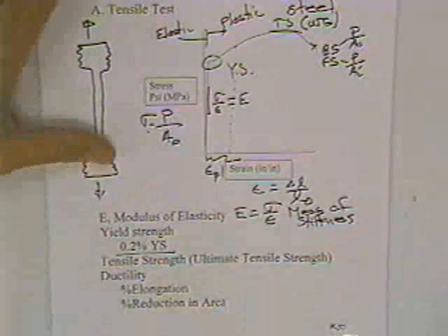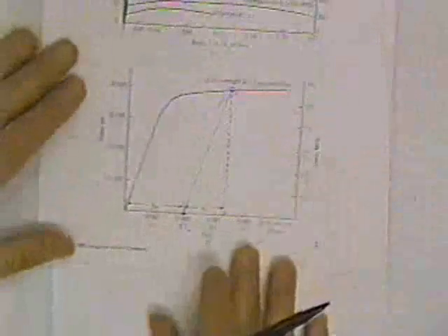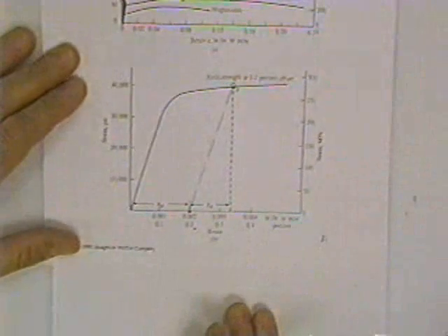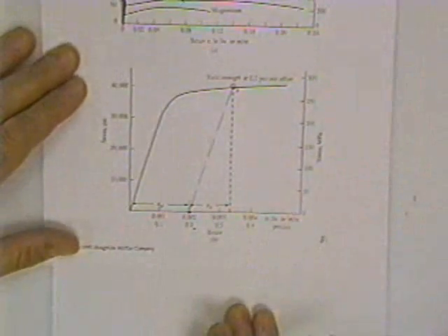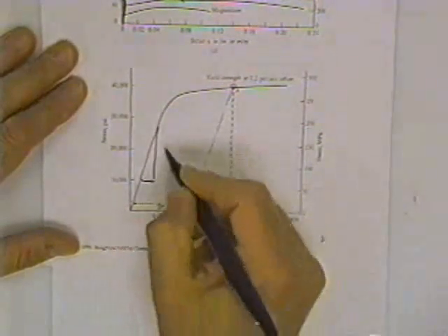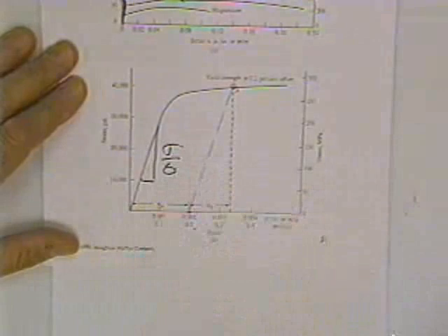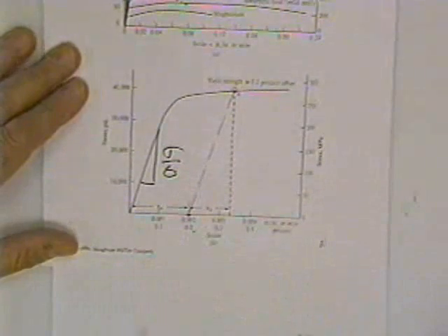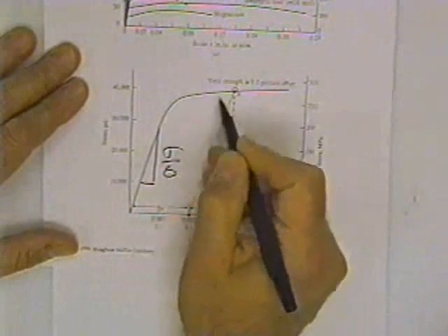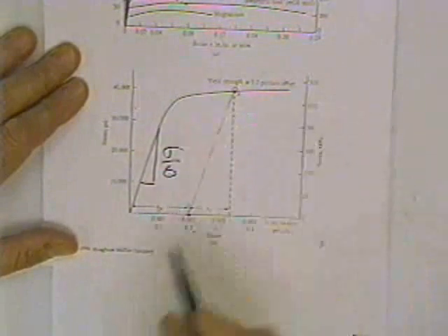And if you go to the second page, page 31 here, there's an example for an alloy showing the 0.2% offset yield. Here's the elastic portion, would give you the Young's modulus, and now you would say, well, where's the yield point? If 5 people did that, you'd get 5 different answers.